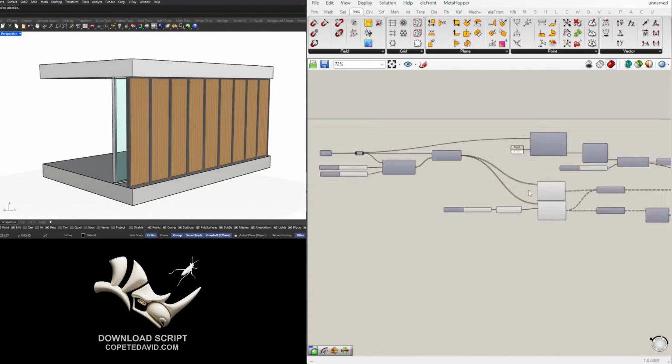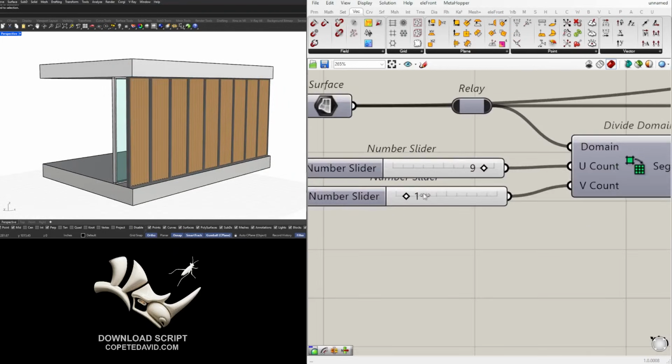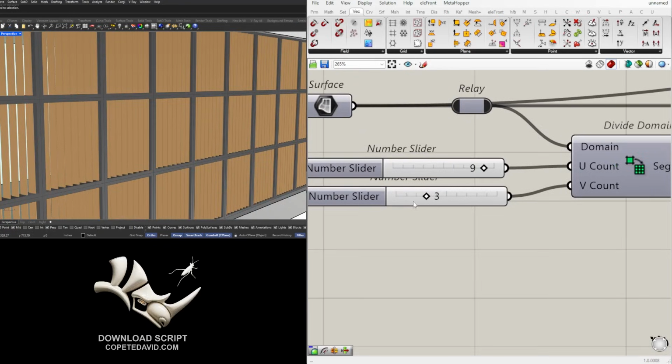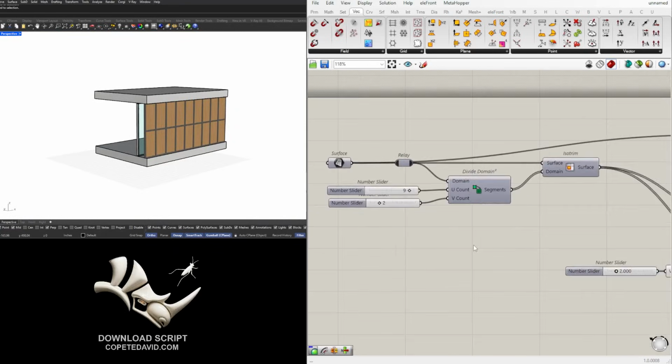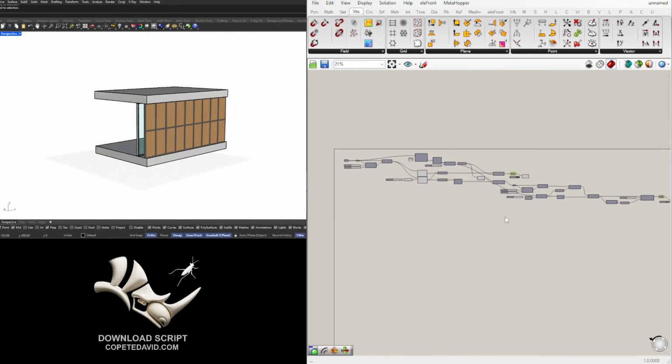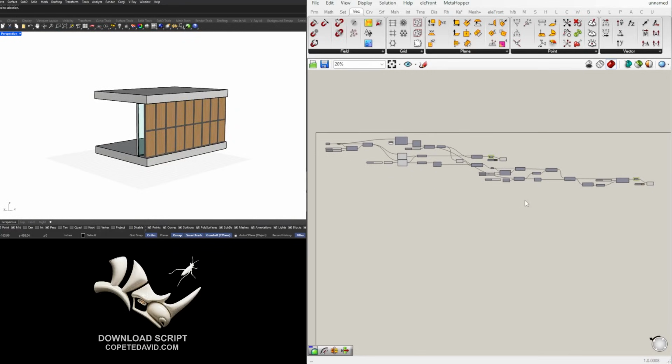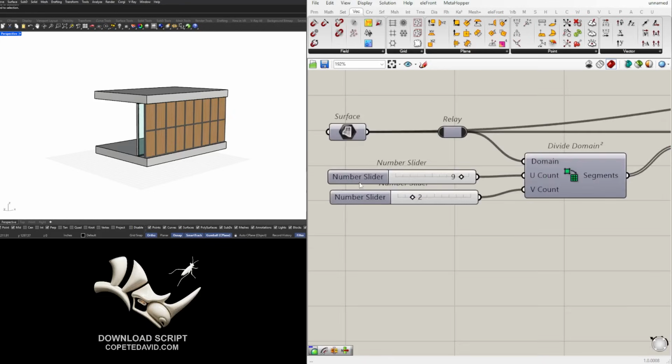And so we have all of these parameters that we can play with. We can create another subdivision here by doing 2 of them. Really that is the power of using something like Grasshopper: if you know what you want and you want to be able to see all the different options depending on what final outcome you might want, this will let you see all of the different options. So let's organize this by going to, this is going to be vertical.